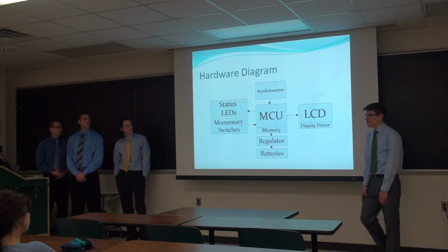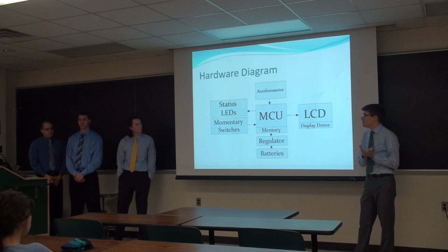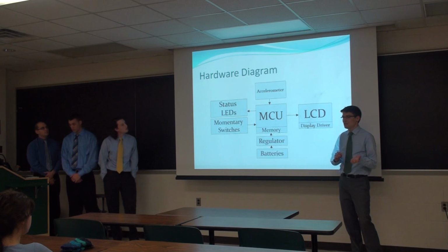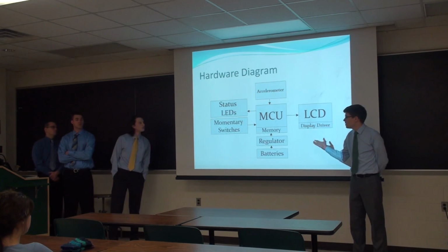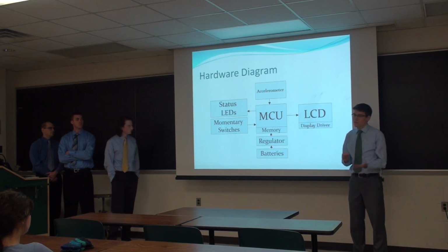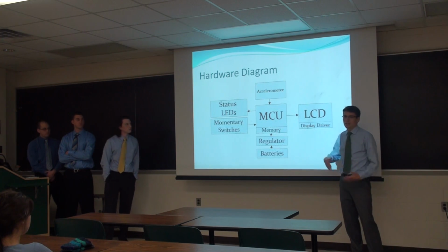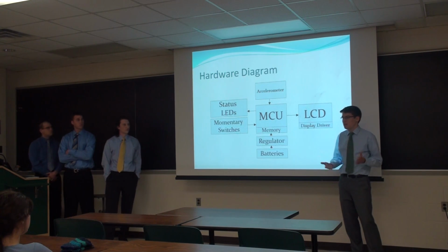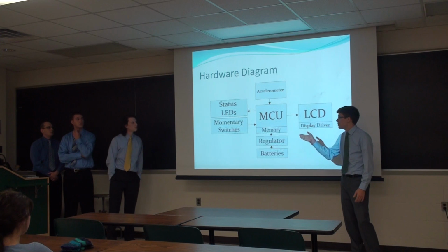Because Instrument Sensor Technologies provided us with a very rigid and complete set of design guidelines, many of which Carl just discussed, a lot of our proposed design solutions had a highly similar high-level hardware topology to the diagram you see here. A lot of the design decisions that we've made up to this point have involved selection of vital components like a microcontroller and LCD, and then either including or omitting a lot of non-vital components. Some of them that made the final design were status LEDs and momentary switches.